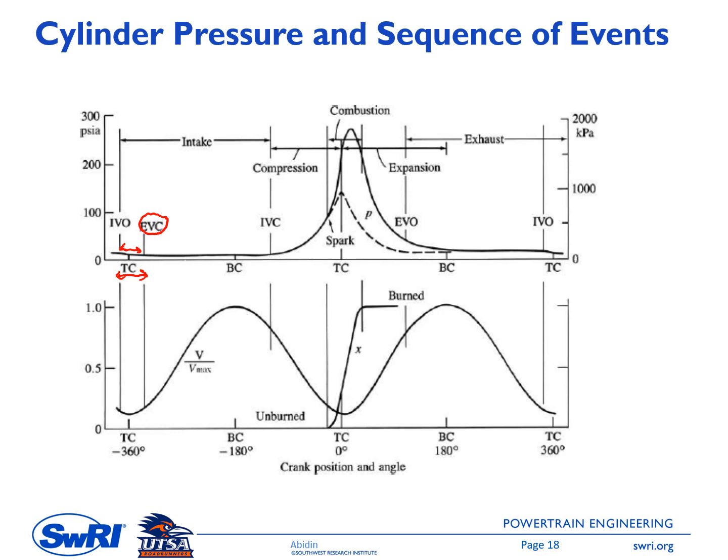It means some of the fresh gas might flow out of the engine directly because of this valve overlap. Why do we need to have IVO before the piston hits TDC? Because we want to maximize the entrance of the mixture to the cylinder.